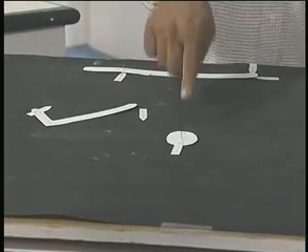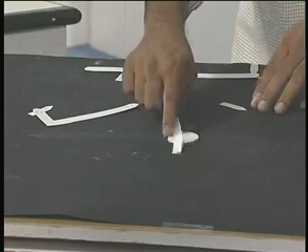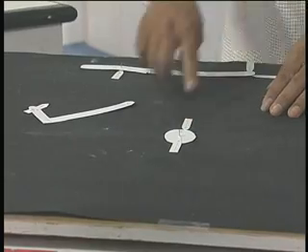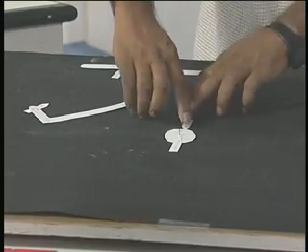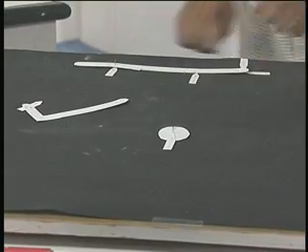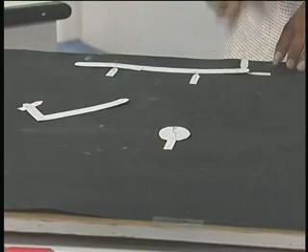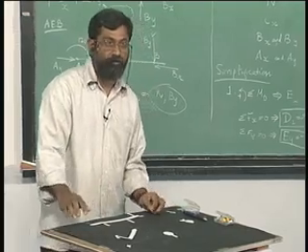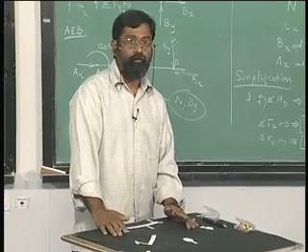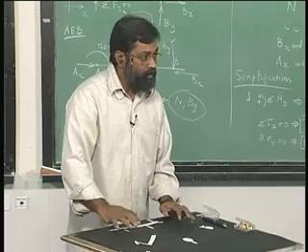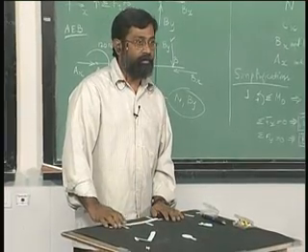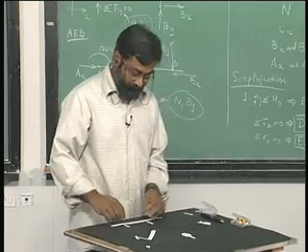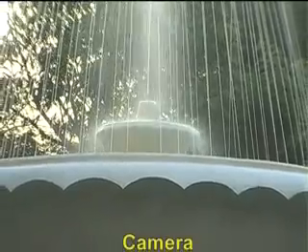At E also I have one restraint that comes from the wheel. Okay. I have used something like this, so this is E upward, equal and opposite reaction occurs here, and this is the free body apart from the moment that occurs at A. This should be very clear to you. Try this exercise a few times to get a physical feel of how to draw the free body. Once you become a master at free body diagrams, then a lot of things can be accomplished in a very simple way. Thank you.